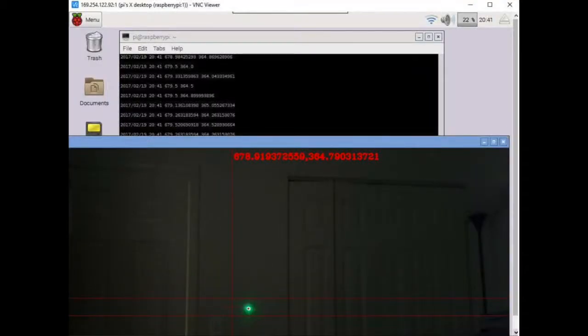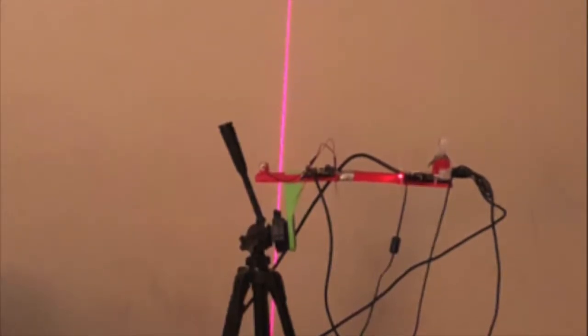The LiDAR system built in this course uses geometrical and triangulation techniques to measure distance from an object. By taking an image, we can measure the perpendicular distance in number of pixels from a laser point to a central datum axis. By using simple geometry, this distance and a known separation distance between the laser and camera, and also taking into account small amounts of error, we can calculate the distance from the source to an object. Since a line laser is nothing more than an array of single laser points, we can extrapolate this method to gather an array of measurements along a line.